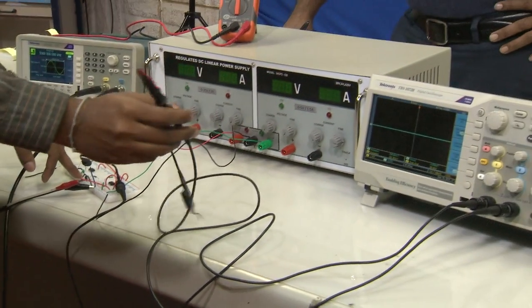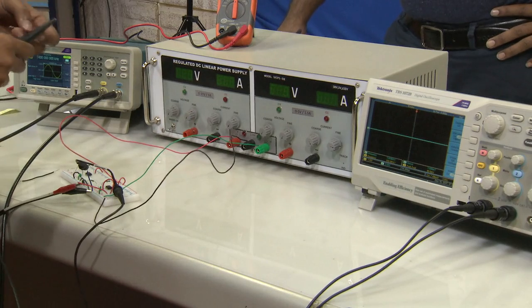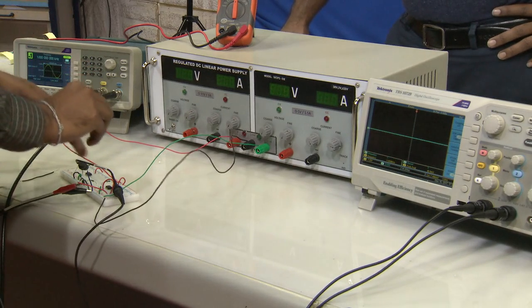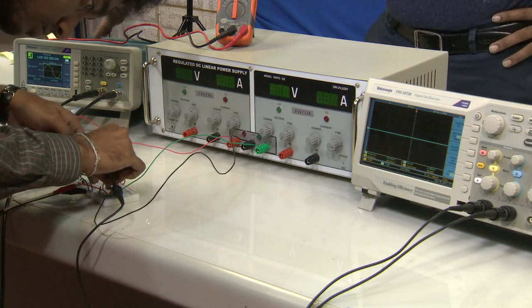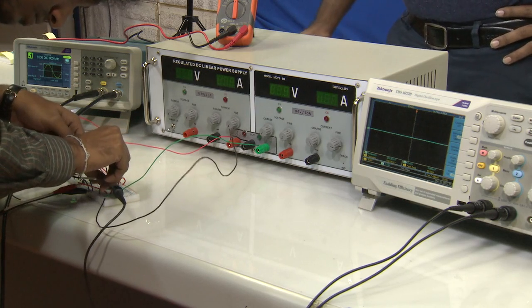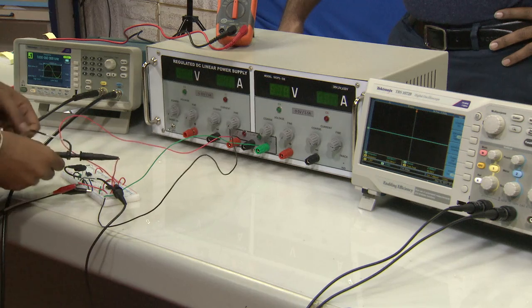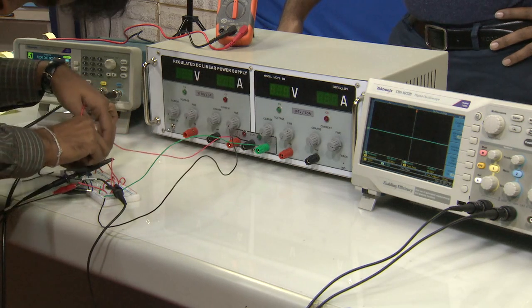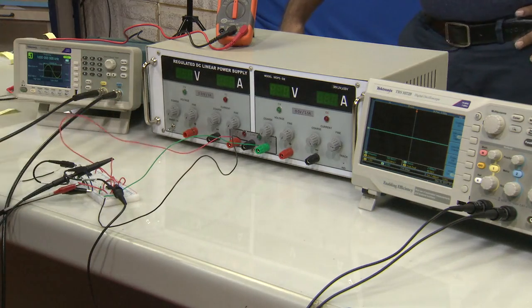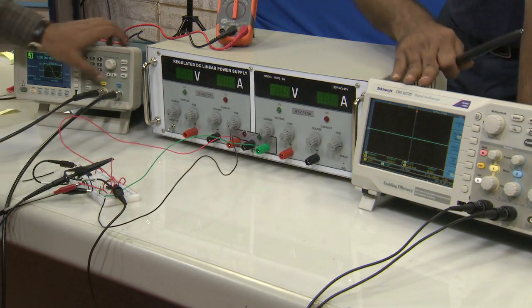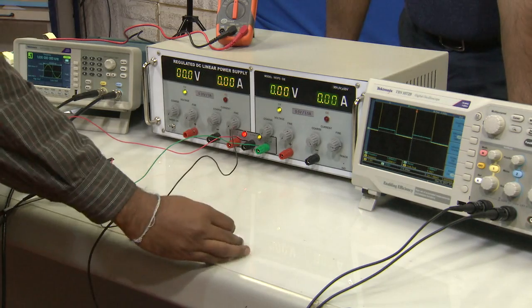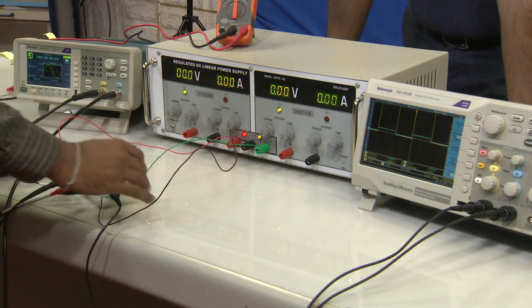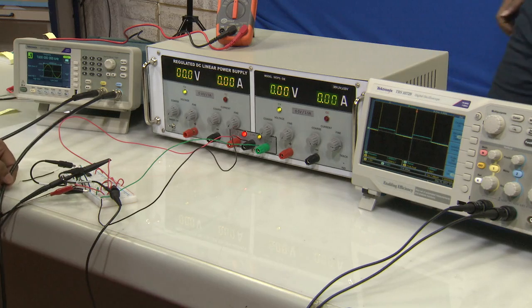Excellent. So, now what we are expecting when we connect this is that we will be able to see the output signal when we apply an input signal of 1 volt, 1 kilohertz. Okay. So, now the circuit is connected, and we have to look here. You can see that when the power was not on, you were not able to see the signal. So, do not forget to apply the bias voltage; without bias voltage you cannot see the signal.